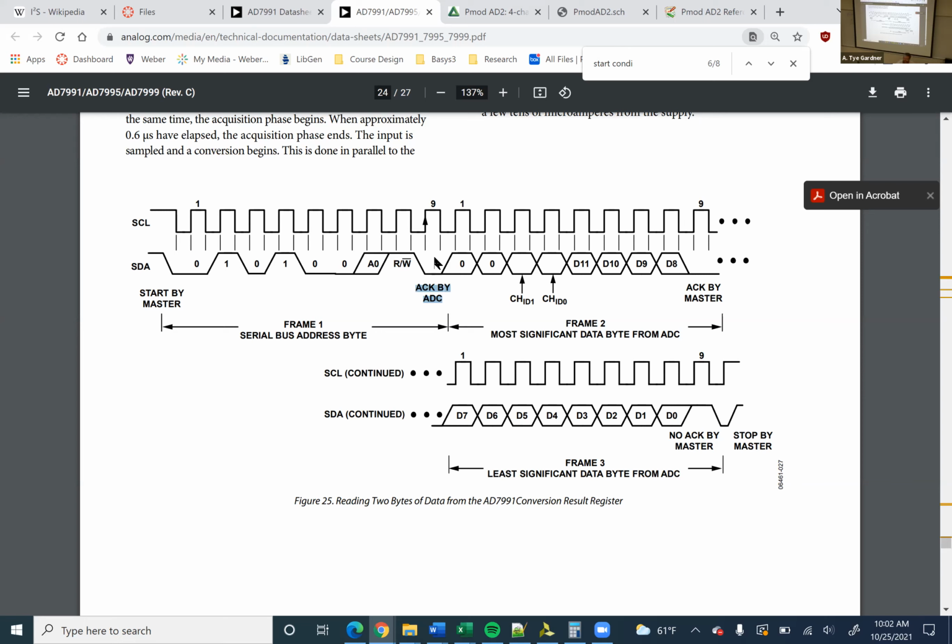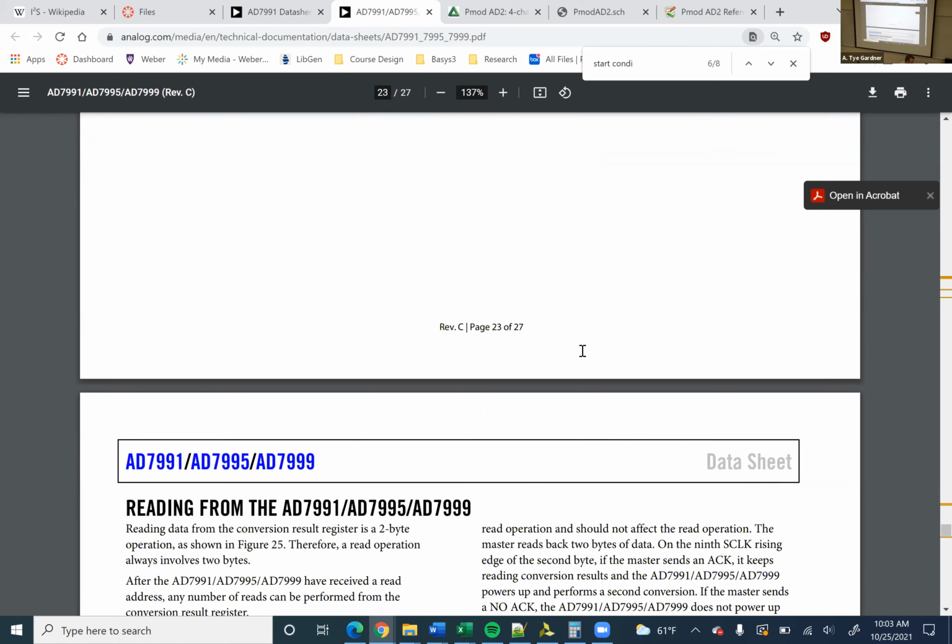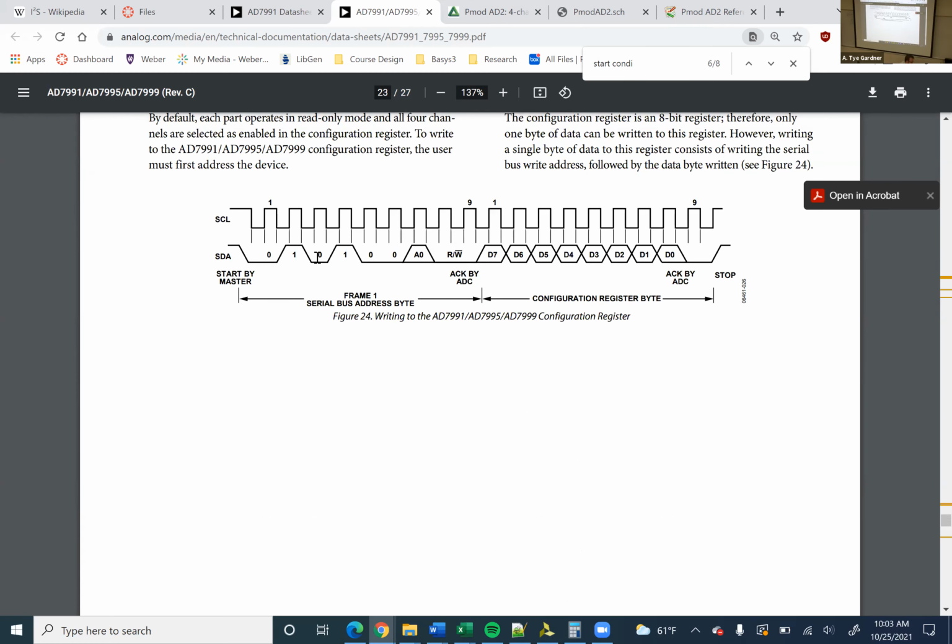And then for 1 clock cycle, you have to go into read mode. Same line. So you have to turn off the enable of the mux to allow data to come in. So you write, disable your output, read the input, and then go back to writing. Well, actually, in this case, if I'm in write mode, send the byte, tell it we're writing, and then send a configuration register byte. And then stop. Write is do this one thing and then stop.